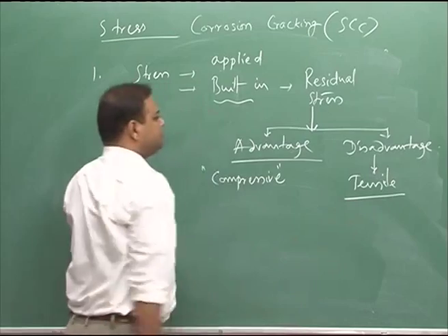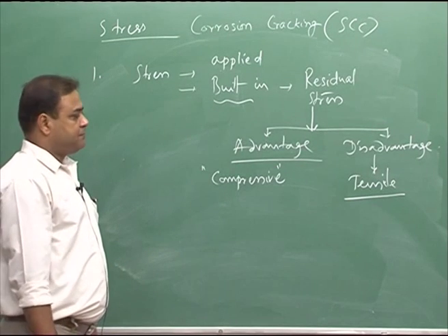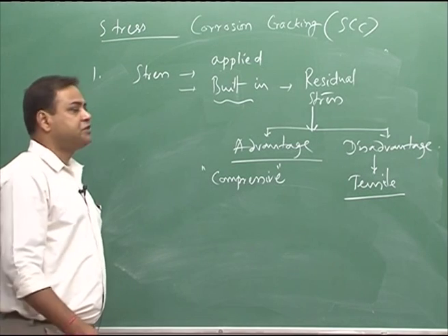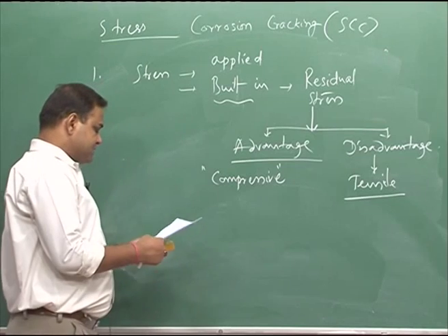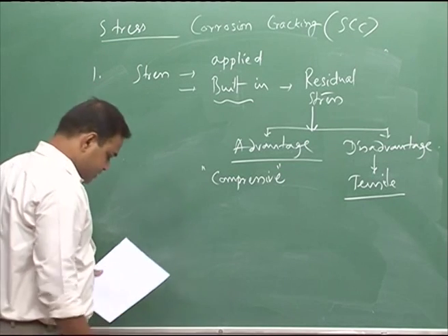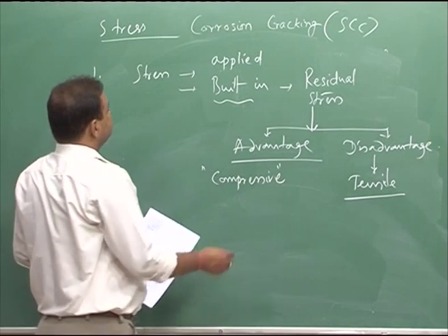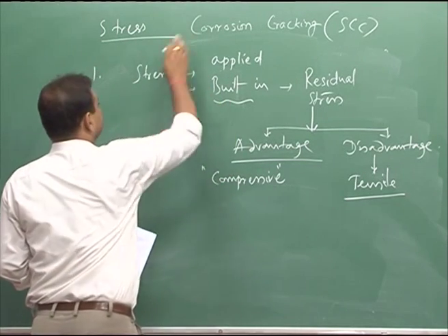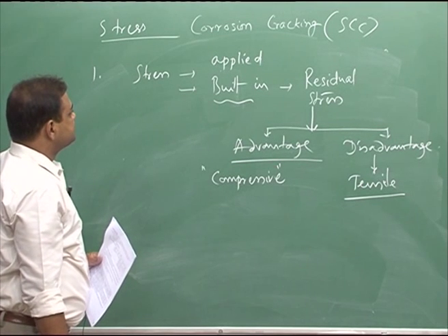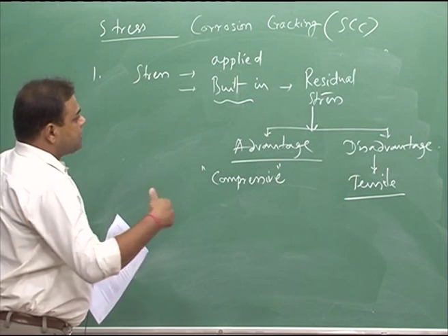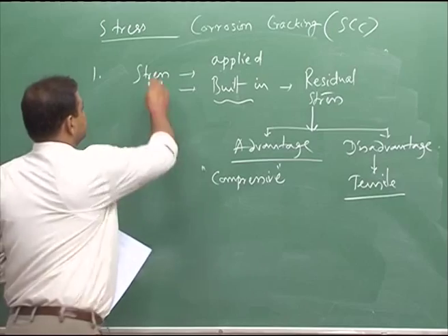Now, if the material does not have any load, but during processing, for example casting or heat treatment, it could develop residual stress, and that residual stress can act in the presence of corrosive solution, and there could be insidious or sudden cracking of the metal object due to stress corrosion cracking.